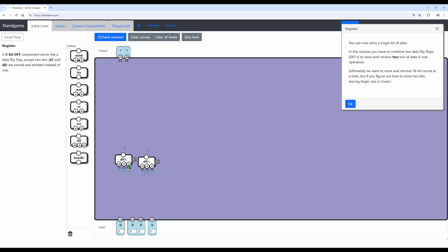That's it. So clock, and this, by the way, is where clock comes in useful, because now you can see it synchronizes both of them at the same time. So this data flip-flop won't basically get ahead. It'll wait because the clock has to update. Then this data flip-flop will have to update as well. So that's why you see the clock starts to become useful once we get into stuff like registers. Even though it can be accomplished with latches, but again, the timing is just weird.